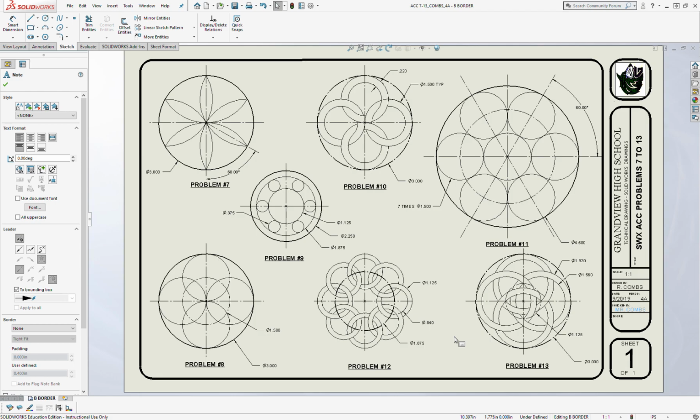So to print, as a rehash, go up to the little print symbol at the top, print. Now what you're looking for is GBH L108 TE Lab. Okay, I want you to go to page setup and just double check that the first box is B border, the scale is at 100%, and it's on 11/17. If it is, you're ready to print. Just say OK and hit OK again. Take your finished drawing, fold it in half, and put it in the gray box.